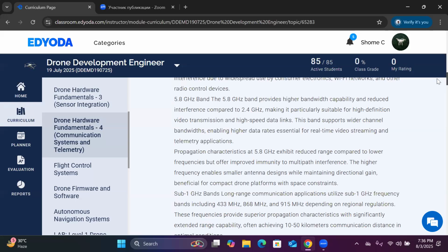Otherwise, what will happen? We will not get the true data in real time. We will get a lot of garbage data, because your receiving station is at the ground control station, the communication box, that will be communicating with the communication module on the UAV. In the UAV, you are connecting a directional antenna. So where the pattern of the directional antenna is, at which inclination or angle it is transmitting the data, that is very, very important. From the data sheet, you need to figure out that parameter or value, and accordingly move your communication module, communication box.